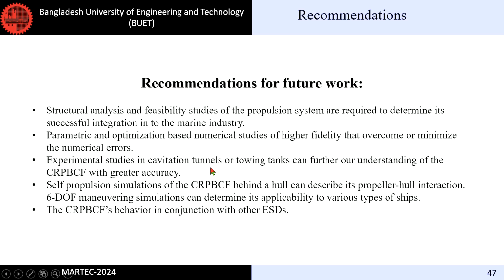Experimental studies in cavitation tunnels or towing tanks can further our understanding of the contrarotating propeller boss cap fin with greater accuracy. Self-propulsion simulations of the contrarotating propeller boss cap fin behind the hull can describe its propeller-hull interaction. Six-degree-of-freedom maneuvering simulations can determine its applicability to various types of ships. The contrarotating propeller boss cap fin's behavior in conjunction with other ESDs.